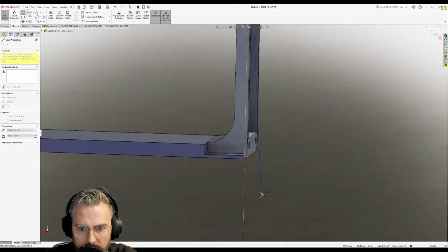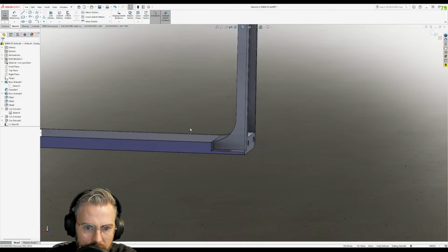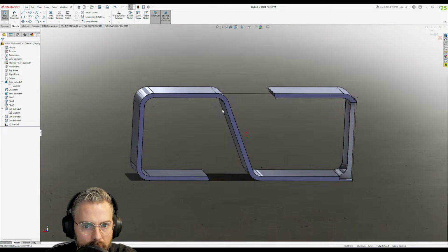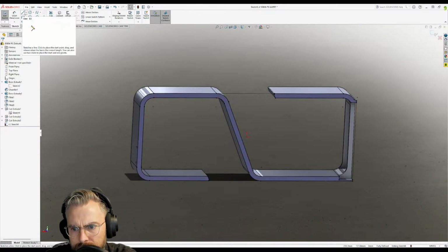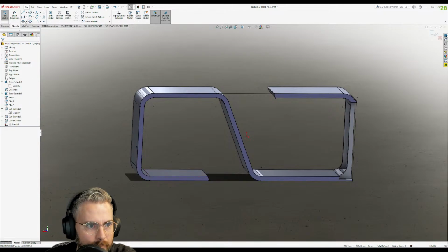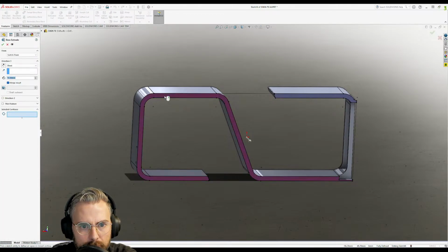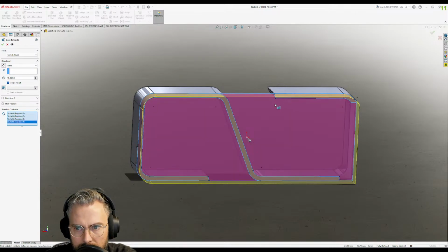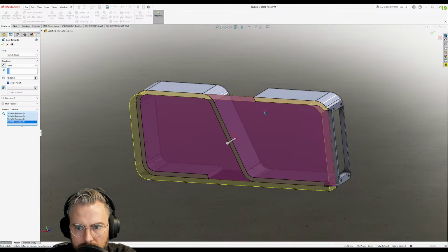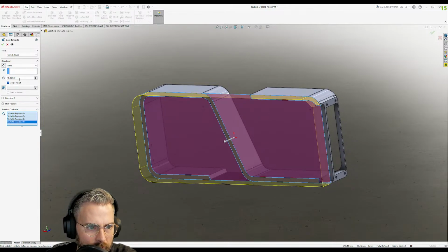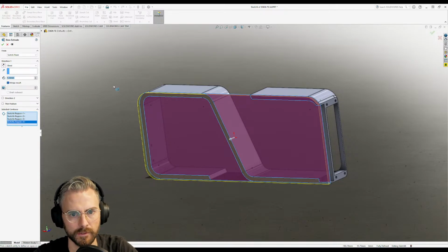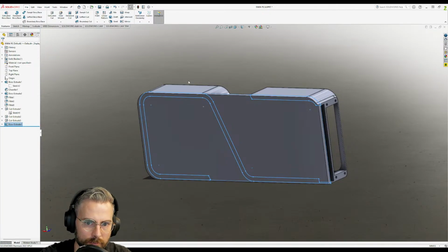And you're going to see, because we want to fully encase our, because we're going to extrude a whole block coming back 4.25 mil. So we're going to do that, and oh, okay, we do have that fully encased now. Yeah. So extrude boss slash base. We're going to go there. We're going to go there. Going to go there and there. And this is going to go back 4.25 mil. And that is basically going to be our back plate.